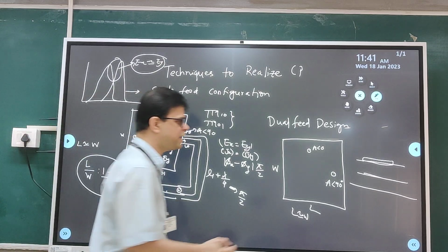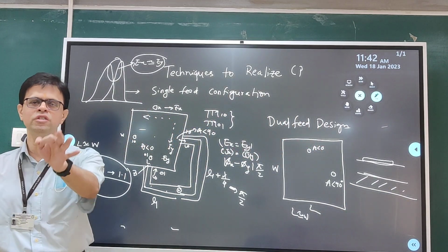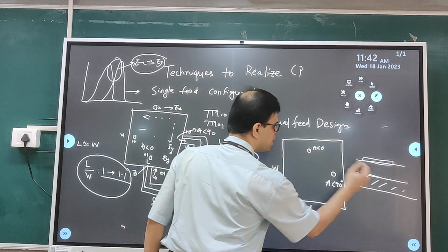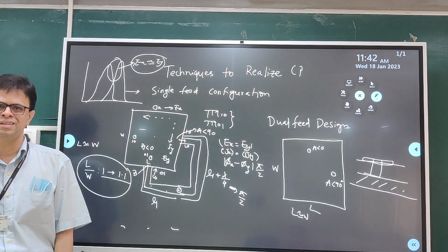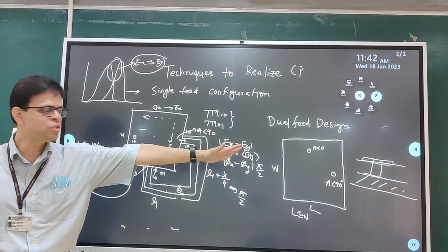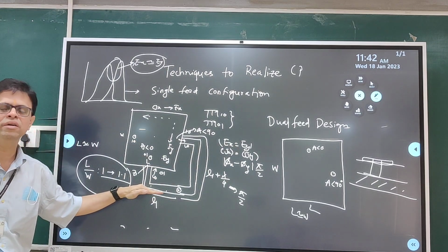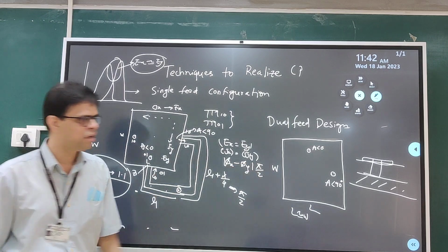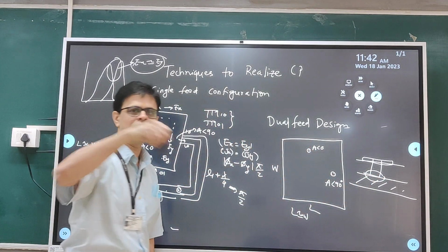So the substrate at the bottom can be chosen such that it is optimized for the power divider circuit, and then these two connections will be brought to the patch through the shorting wires. Generally we use this kind of feed network to ensure that the effective radiation problem from the microstrip line is minimized.